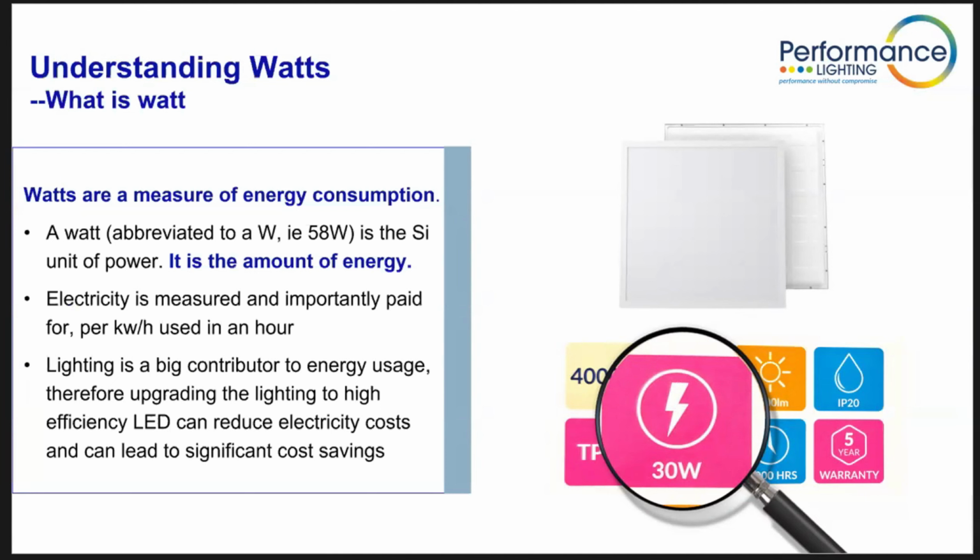And electricity costs have obviously increased very dramatically over the last few years, as everybody knows. Probably doubled and trebled. So 50p, maybe 60p, 70p per kilowatt hour these days and upwards, which I suppose when you think about it, 1,000 watts costs you 70p per hour to run. Doesn't sound a lot, but if you're using 30 kilowatts or 100 kilowatts of lighting in some big installations and more, lighting suddenly becomes a big expense.